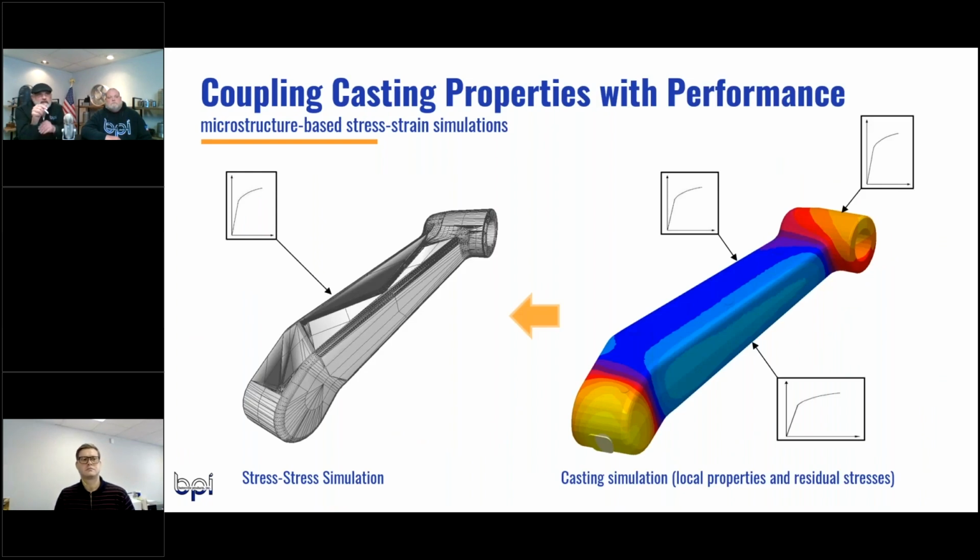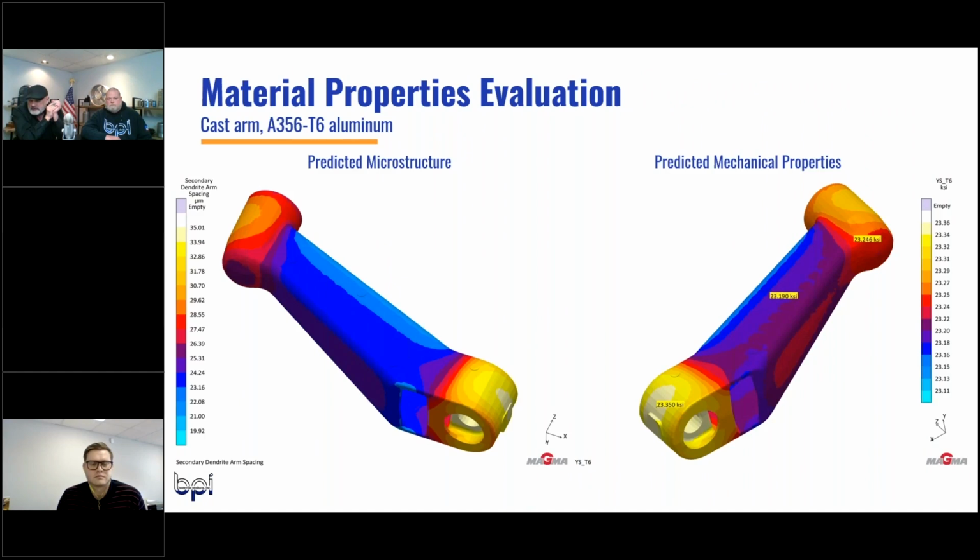So, Vadim, we talked about this earlier, but this is showing you different mechanical properties throughout that cast part. Does that same type of situation also exist in an extruded part? While the mechanical working, the direction in which the mechanical deformations are applied, are certainly going to produce non-uniform properties throughout the part, the distribution there may be more predictable and controlled, in the sense of knowing that we're starting out with an ingot and then working it in a very controlled environment. But again, that is also important. Extrusions, stampings, forgings, there's a slew of simulation packages that provide a tremendous amount of information to the designers as to the strength and durability of their components. So it's critical to look at those processes as well, and not assume that your properties are homogeneous throughout the part. That's a good point.